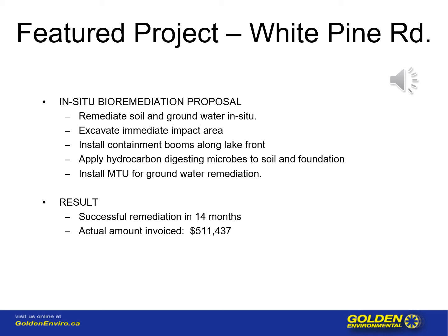The in-situ bioremediation proposal for this site was to remediate the soil and the groundwater in situ, to excavate the immediate impact area, to install containment booms along the lakefront, apply hydrocarbon digesting microbes to the soil and the foundation, and install a mobile treatment unit for groundwater remediation.